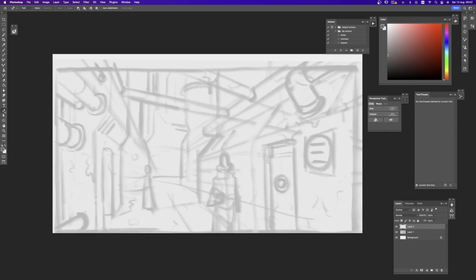Select the pen tool and make sure you're working in path mode. I'm going to roughly eyeball where the horizon line would be based on the information I already have. Just draw a line with 2 points, then click on Horizon inside the plugin window. If you're happy with what you got, let's move on to creating some vanishing points.